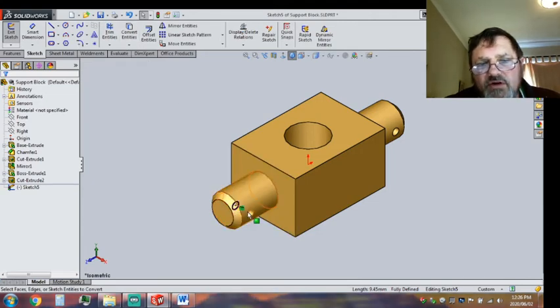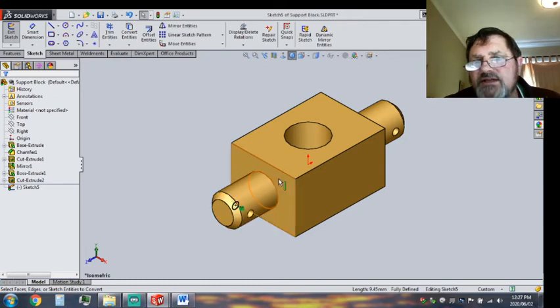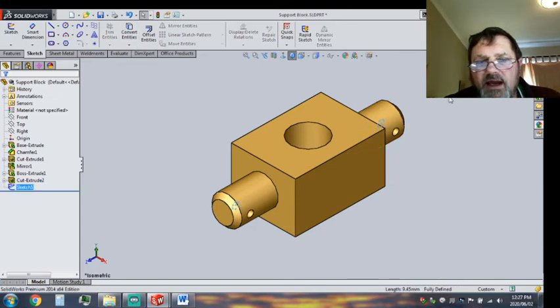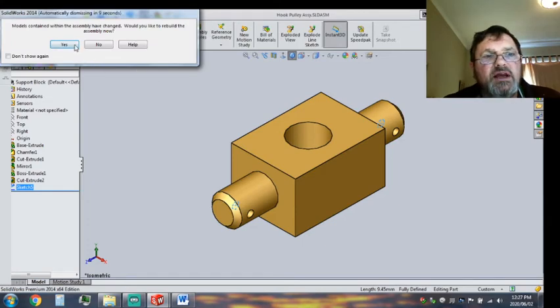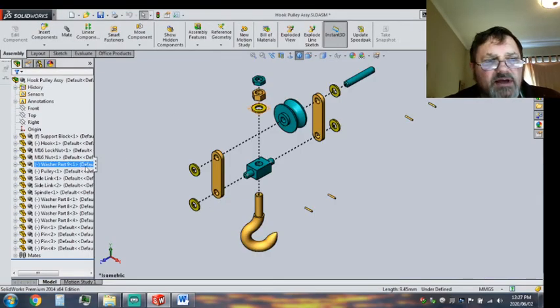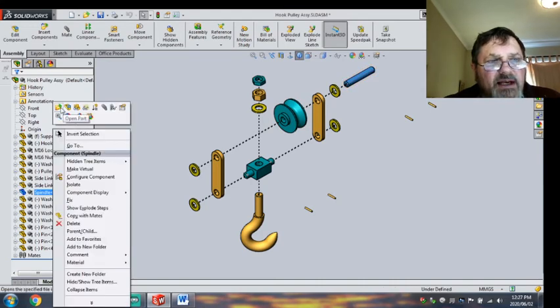Gives me that circle. So it projects that surface onto my sketch as a circle. I can do the same here. Convert entity gives me there. I can say okay, and I can leave that guy visible. I can go save, close. Yes, update my sketch, and I can go for the spindle and do exactly the same.